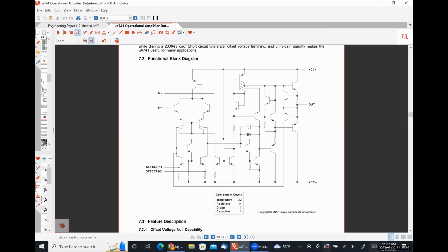There's only one output. So an operational amplifier is what's called a differential amplifier, because it actually amplifies the difference between these two inputs, or at least that's arguably what it's supposed to do, but we use it for lots of other things and practically never that. We use that for comparators. We'll talk about those on Monday, right?